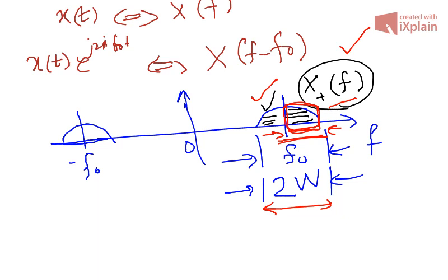Now we would be interested to find a baseband signal whose passband spectrum is just this one. What should we transmit, what should be the baseband signal whose passband spectrum is just this one? It's just saving your bandwidth, just W. You'd be interested to transmit only the signal with W band instead of 2W, which is twice, and bandwidth is very important in communication.